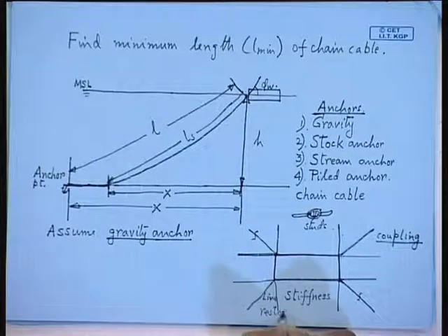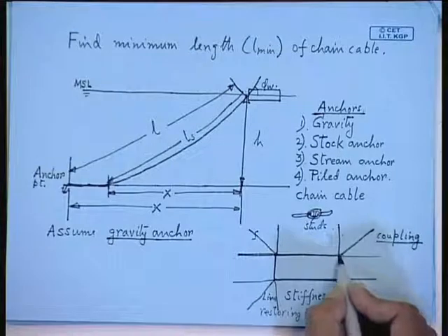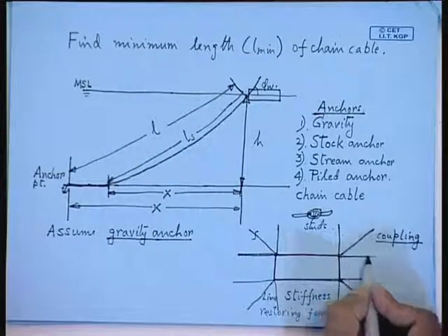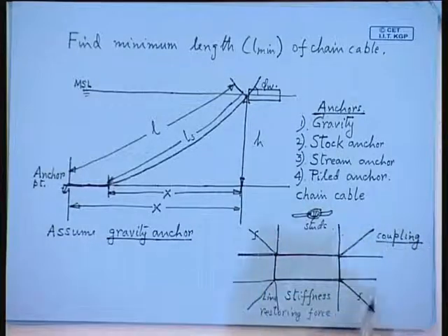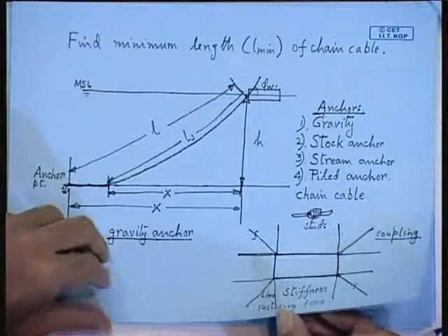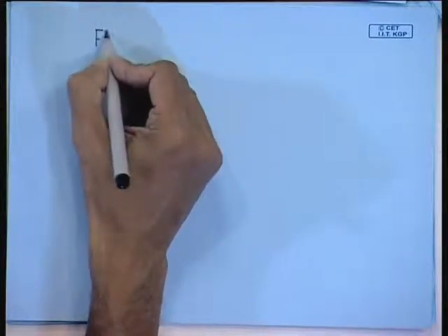So you can see the mooring analysis is quite complicated. In our class, the example dealt with only one line, but ultimately you will find you have to make a dynamic analysis with all these chain cables. Normally if you start doing this expression, you land up in a finite element idealization or a matrix form of equations. So ultimately you come into a FEM analysis.